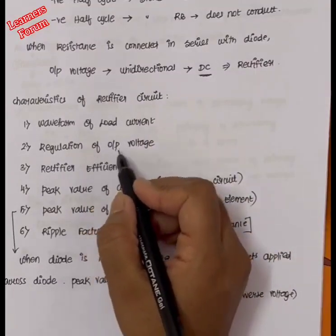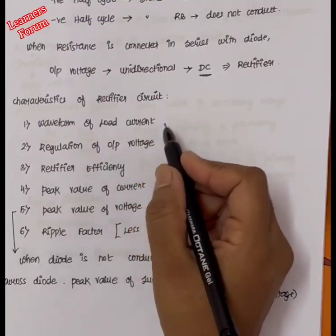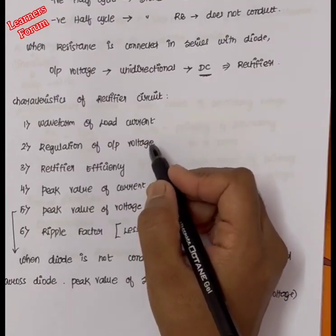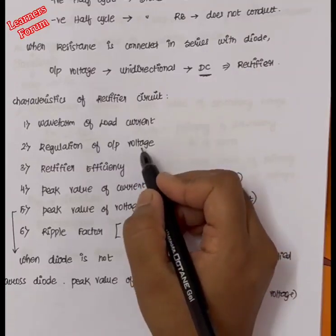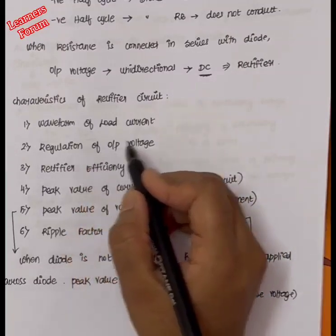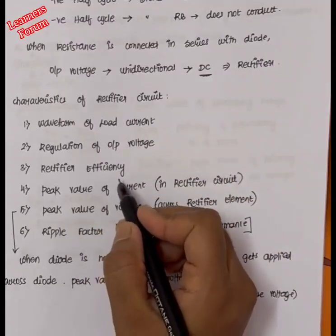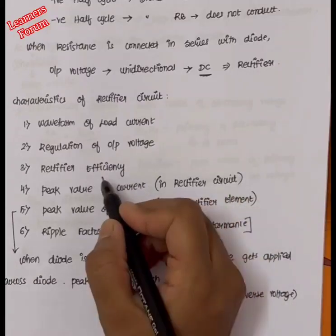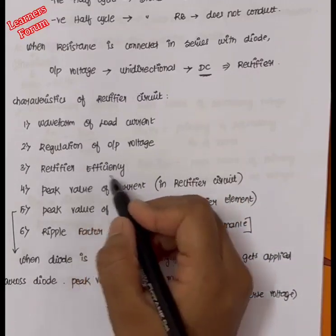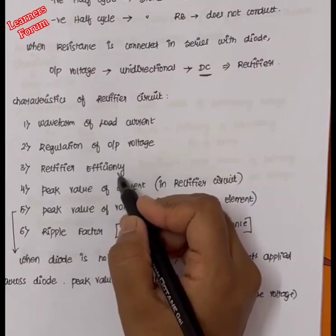Second is regulation of output voltage. Again, when there is a variation across each element, say if we are using a diode, there will be voltage regulated over here. In that condition, we have to check the regulation of the output voltage also. Third is rectifier efficiency. How much output we are obtaining and how much input we have applied, the ratio will be taken as rectifier efficiency. We have to calculate the efficiency, based on which we can detect the performance of the rectifier circuit.